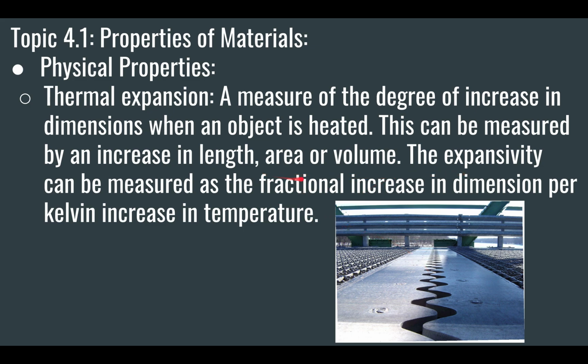So thermal expansion is the measure of how much something will expand, and of course, different materials will expand by a different amount depending on their properties. It is definitely something you want to pay attention to when designing. If you're designing something that is going to be in an environment with a lot of temperature change, and it's prone to lots of thermal expansion, then you're going to want to design in something that will allow that thermal expansion and contraction.